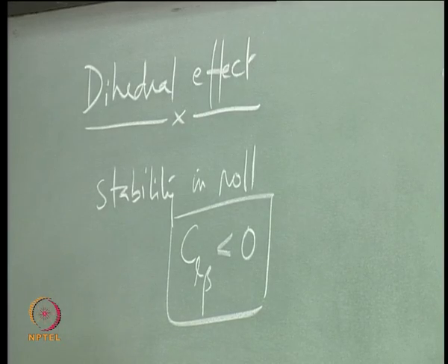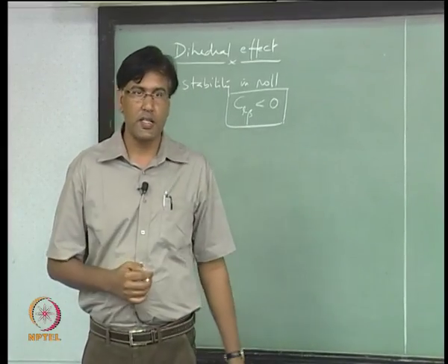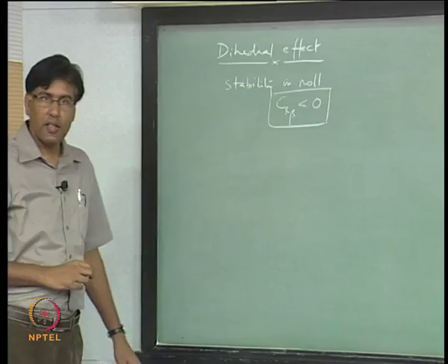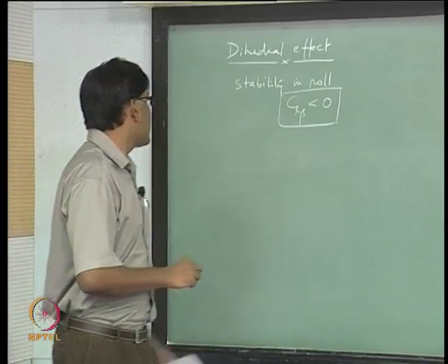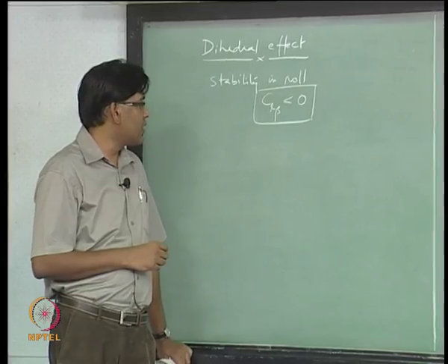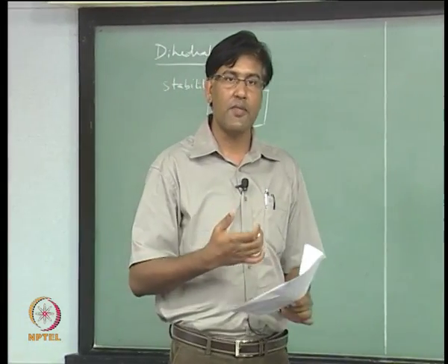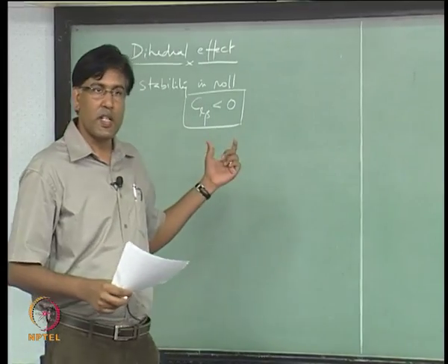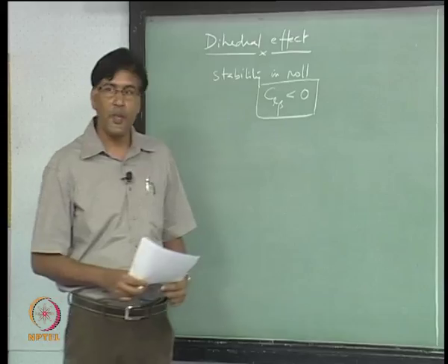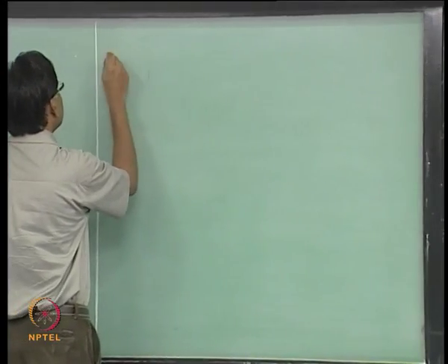We will discuss mainly the wing contribution in this class and see if there are other effects which are also prominent and worth discussing. We will look at how wing position on the aircraft can give you this CL beta. So, mainly wing contribution to CL beta is what we are seeing here.